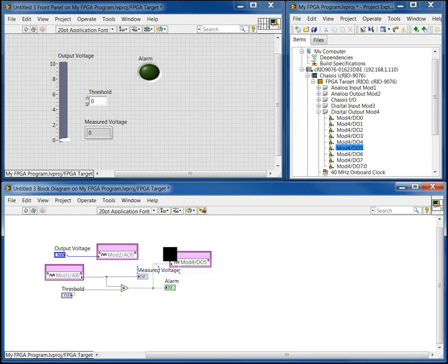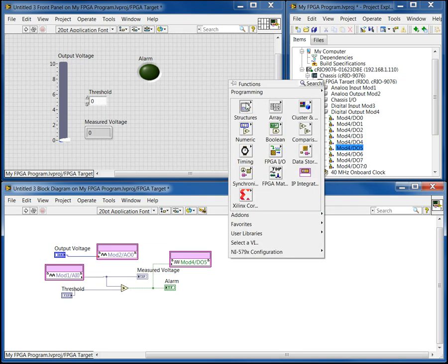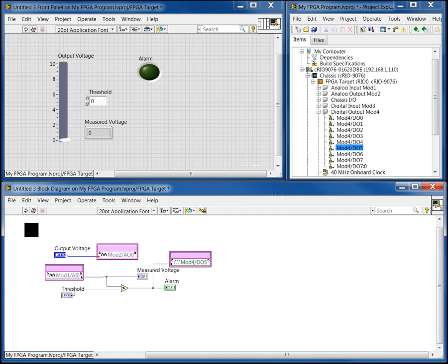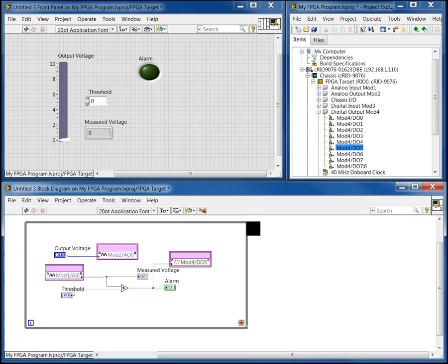Okay, and the program will not be complete if, let's say, you're running it just once. I want to have the consistency of running this program to keep on running until I stop the program. So I would like to add an additional structure to this program itself. So I will right click and add a structure of the while loop. By adding the while loop, the program will keep running until the condition is met before we exit the program itself.